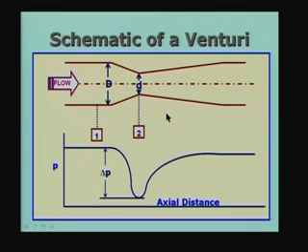And let us look at what is happening. I have just schematically shown the variation of the pressure along the direction of flow. The direction of flow is from left to right as shown here, and the pressure is uniform until it comes to the variable area section and starts reducing. At section 2 it has the minimum value because the velocity is highest here and the pressure has come to the lowest. In the diverging section the velocity again starts decreasing and the pressure starts increasing.